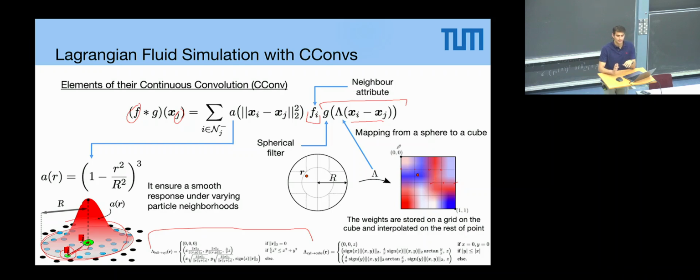Okay, so once we have transformed our node from here into somewhere in this new domain, we can get the value for the kernel there. We are only storing the values at discrete locations, and if we want to get the value at this intermediate location, we just do bilinear interpolation. So that way, every point here in this circle is assigned some value for the kernel. What we are doing is transforming the square into a circle, and we have continuous values because inside this square we do bilinear interpolation for the weights. And this last bit here is not strictly necessary for this to work, but it helps to improve the accuracy.